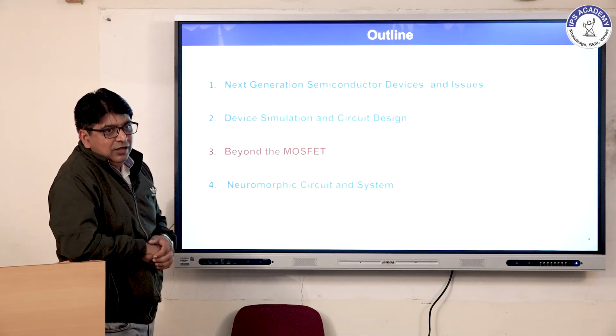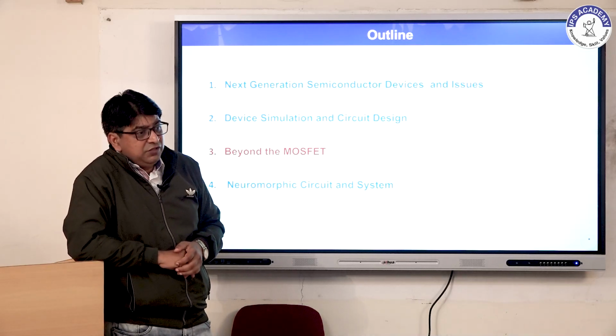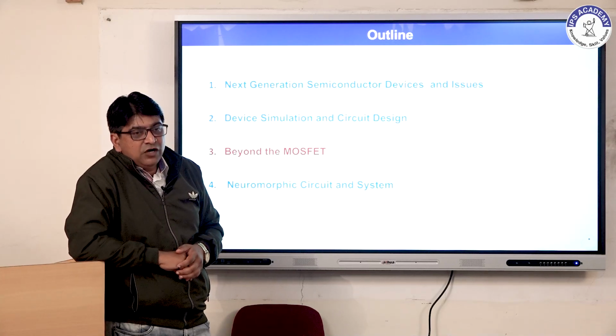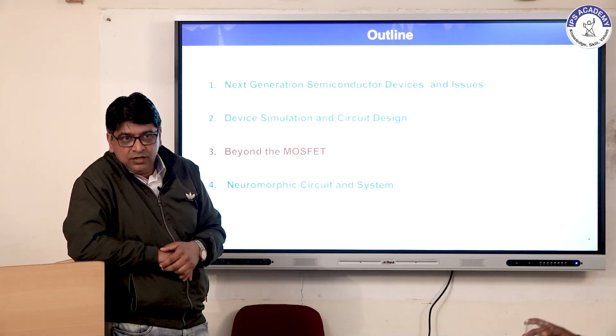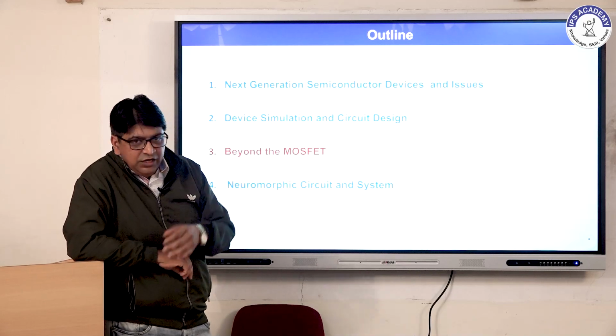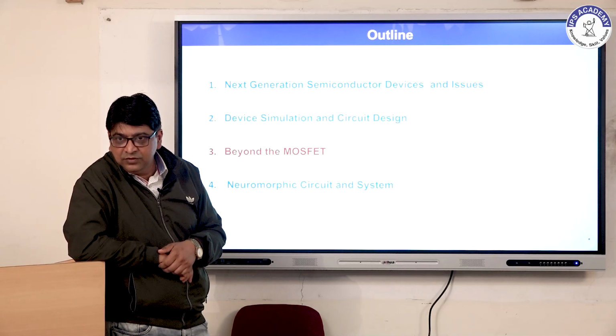Next, why are we searching for an alternative to the MOSFET? The MOSFET works on the thermal injection of charge carriers. That is the conduction concept, and it faces short channel effects. Short channel effects we can improve with the help of multi-gate architecture or device engineering, as I discussed.